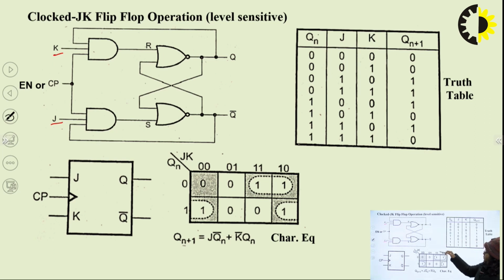So if we do the working of this flip-flop, for each other combination, output is same. We just replace S by J and R by K. So for 0, 0, if previous state is 0, next is 0. If previous state is 1, next is 1, that is there is no change. If reset is 1, output is 0. If set is 1, then irrespective of previous state, next state is 1.